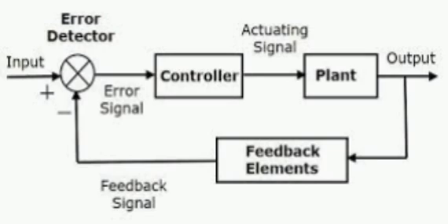Transient response specifications of second order control system: peak overshoot, td, tr, tp, ts. Delay time is the time required for the response to rise from 0 to 50% of the final value. td equal to 1 plus 0.7 zeta by omega n.